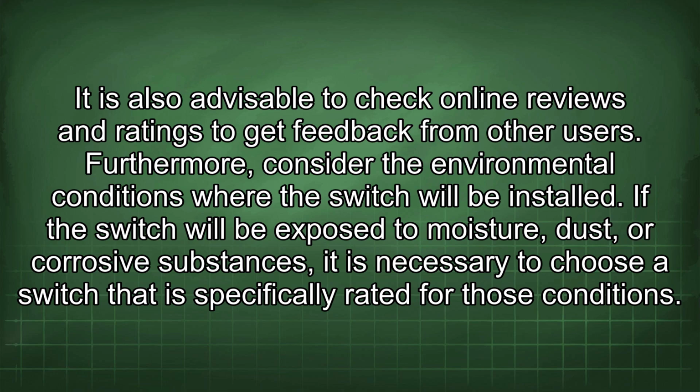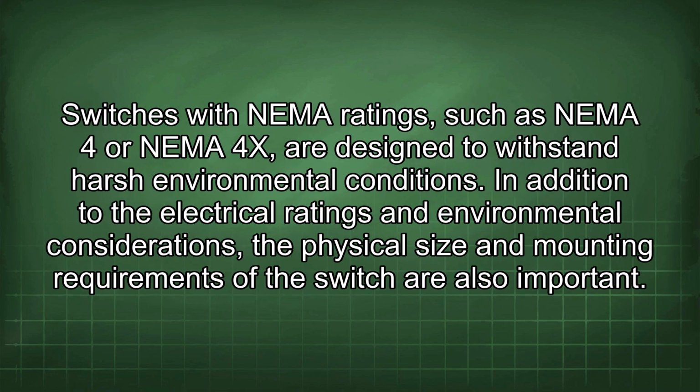Furthermore, consider the environmental conditions where the switch will be installed. If the switch will be exposed to moisture, dust, or corrosive substances, it is necessary to choose a switch that is specifically rated for those conditions. Switches with NEMA ratings such as NEMA 4 or NEMA 4X are designed to withstand harsh environmental conditions.